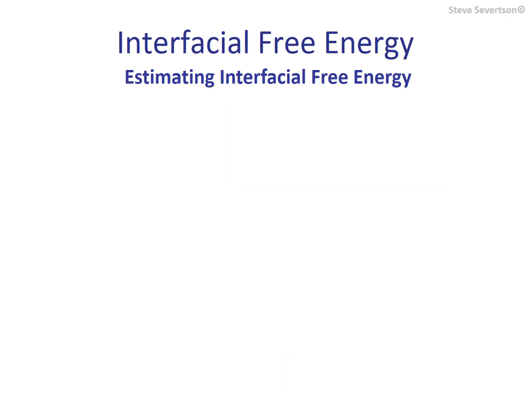This equation is useful for estimating total interfacial energies, but it is even more helpful in that it provides an approach for estimating thermodynamic potentials at the interface. By analogy, we can write an expression for the interfacial free energy in terms of the surface free energies of the phases composing the interface. We've added a correction factor, which provides useful information regarding the interactions at the interface. Here we rearrange the base equation.